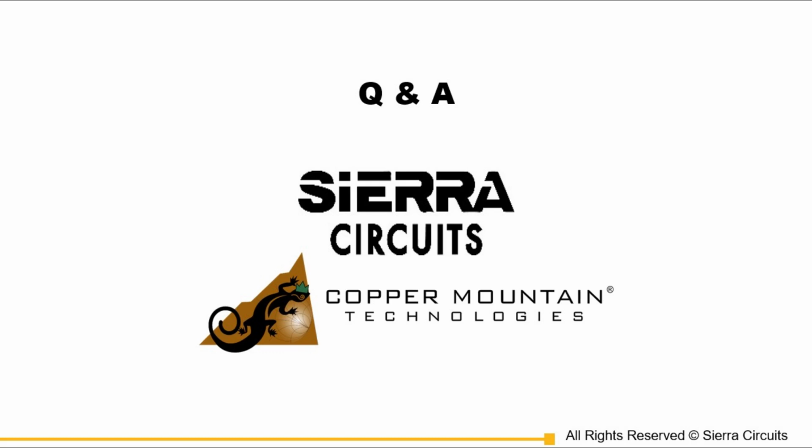I can take the next question about the via fence. I did say that the vias could be a quarter wavelength apart. That really is the bare minimum, and in fact, if you do that, there's going to be some evanescent mode leakage between them. So it would behoove you to do something less than that. The next one says lambda over 8. That's not a bad idea at all. I've seen lambda over 10. So take your pick.